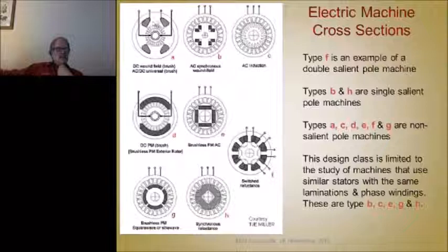The field, or the flux that comes from this electromagnet, can be adjusted. So if you connect a DC power supply across here, you can vary the strength of this field and vary the whole torque speed curve and characteristics of the machine. But on the permanent magnet machine, you don't have near that flexibility because your magnetic field is fixed. It's not adjustable. You can't make it stronger or weaker.